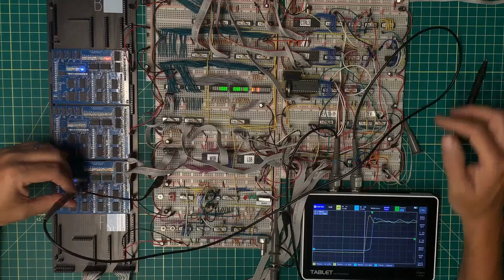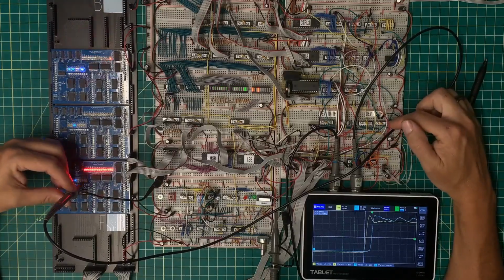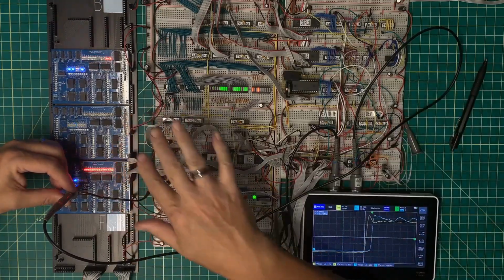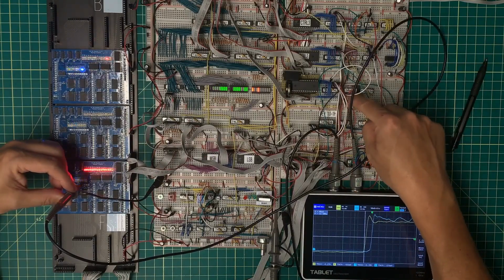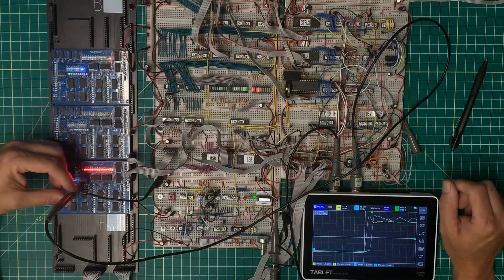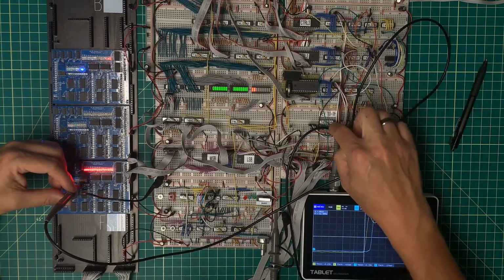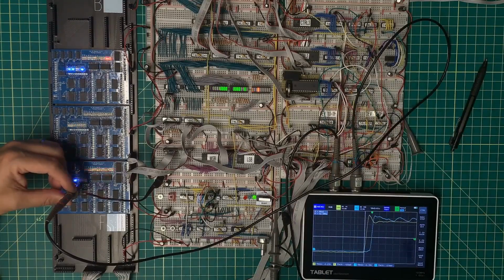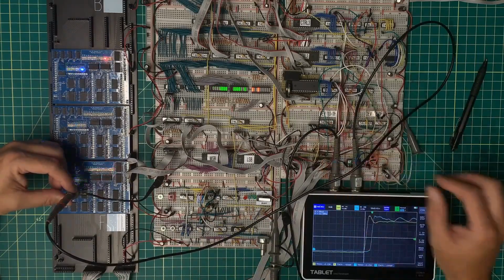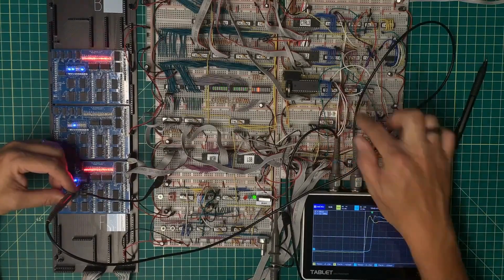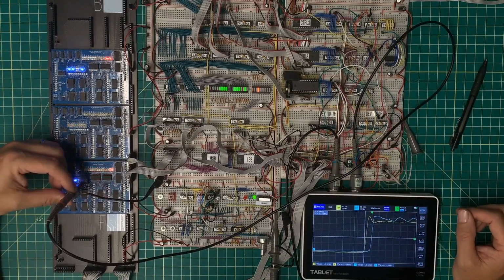Now, that said, I'm still using LS logic here to drive HC logic. I want to replace each of these with an HC version, or this is already an HCT version, so that the family is the same and the outputs are the same, and I should then be able to drive everything with a slightly faster signal. But right now everything looks like it's balanced properly, and this all looks good to me so far.